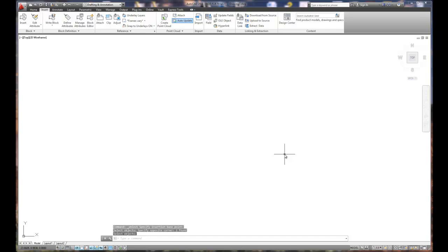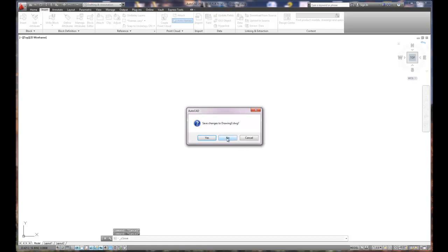So what we've now done is we've created attributes and we've created blocks. Both create blocks, which are good for the single drawing, and W blocks, which are more commonly used throughout multiple drawings. I'm going to go ahead and close this particular drawing, so that way you know that there's no remnants whatsoever of the information that we've been using. So nothing is going to be stored locally within the drawing. We're not going to save it.